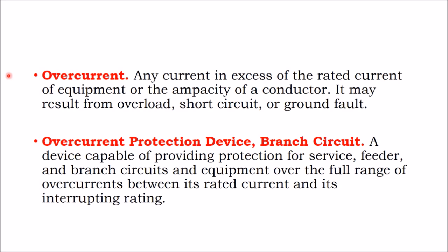Overcurrent is any current in excess of the rated equipment or ampacity of the conductor. What can cause an overcurrent situation? Well, if you plug in too heavy a load, maybe you put 30 amps of devices on a 20 amp circuit, or if you're short circuiting. If that power supply is draining directly into the ground, it's a ground fault or short circuit, which causes overcurrent, even if just for a split second until the breaker switches over.